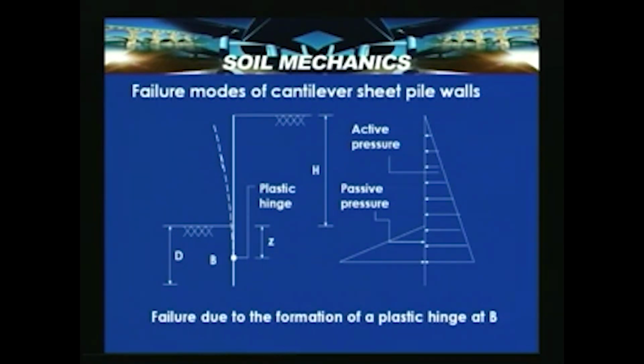That means there will not be any failure or rotation about this point. The wall yields about this point and attains a moment beyond the plastic moment capacity of that section. This is possible if there is an enhancement in pressure and the section is not adequately designed, then material failure of the wall can occur and yield this type of failure.